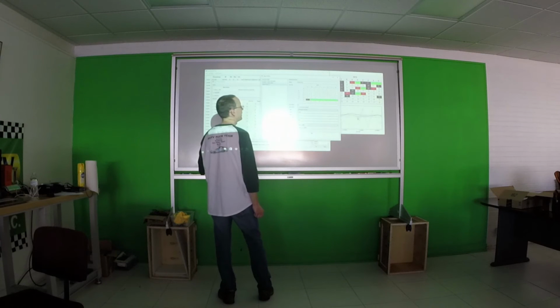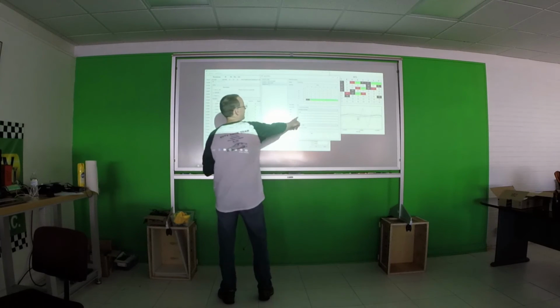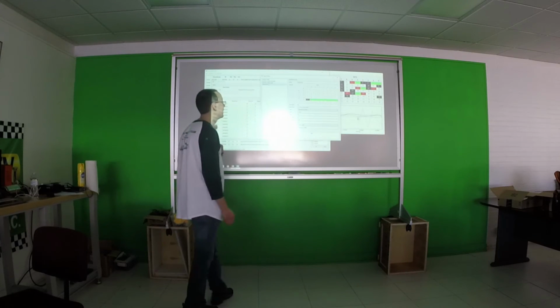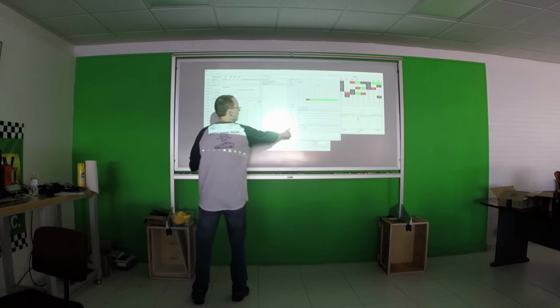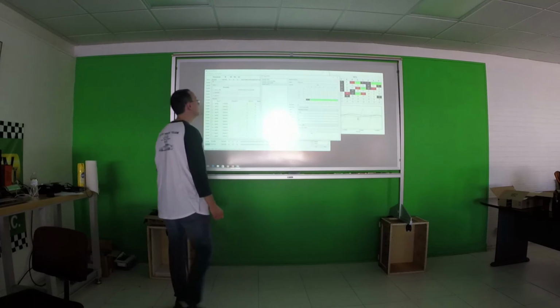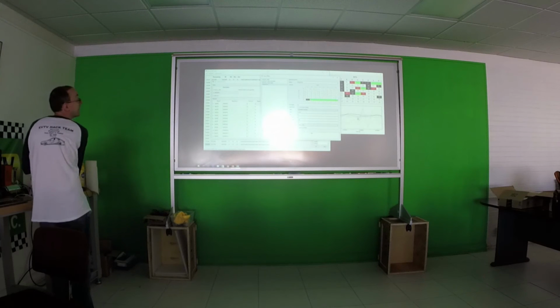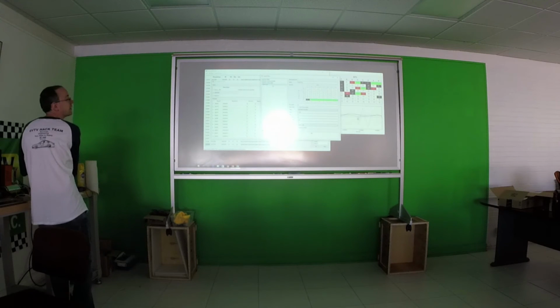That's actually a guess on my part, because the throttle goes from 0 to 255. And this factor turns 255 into a percentage, so it just goes 0 to 100%. I've commented here that it's scaled 0 to 100%. So the DBC, like you said, is a dictionary, and it's a converter. It turns values that otherwise would be complicated.